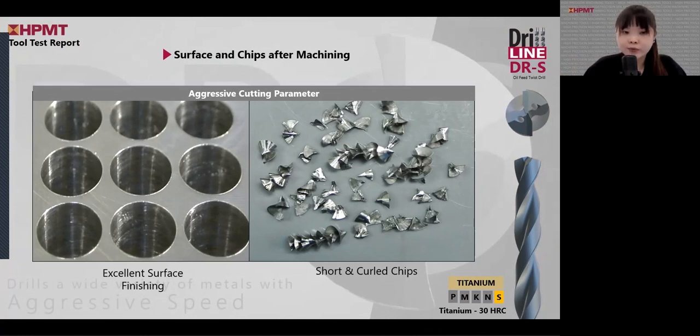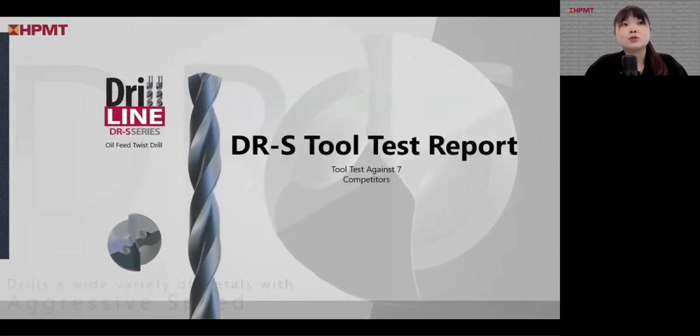So in summary, our cutting tool used in this test is our W11 with a 5D length. After it goes through all these kinds of materials, I think we can conclude that it doesn't matter what material it is, we can still produce a good surface and good chips. Knowing that our cutting tools have no issue dealing with these different ISO materials.